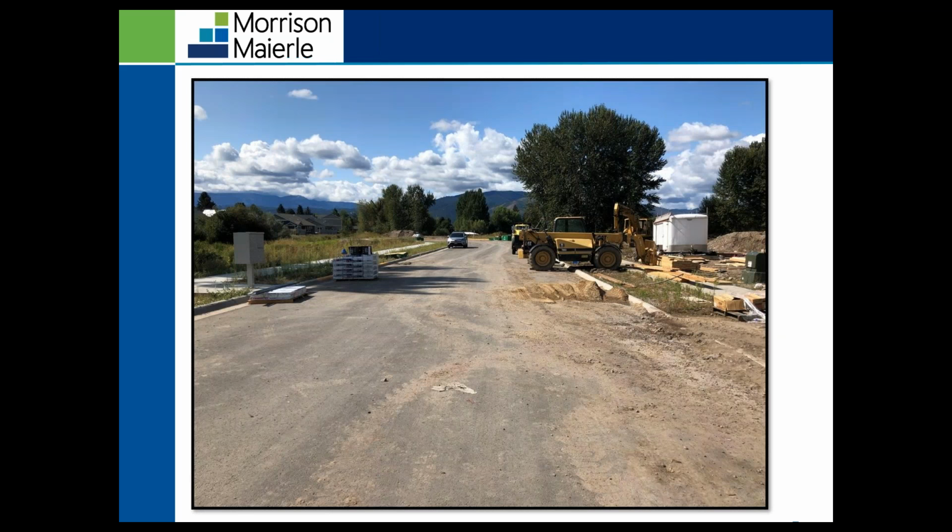So I'd like to show this photo here. This is from when I've been doing my own inspections for a permit. This is a picture of a subdivision with no BMPs implemented on the construction site. So you can see sediment is on the road, there's materials, there's equipment, vehicles that are parked on the road, really no way of containing that sediment.